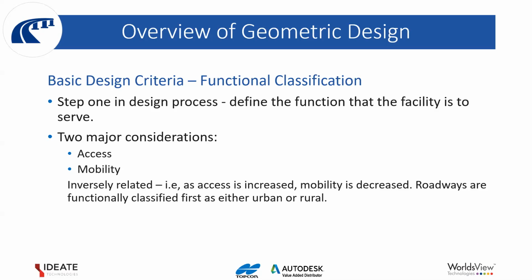In defining those parameters when designing a particular road corridor, access and mobility are inversely related, in that if you want to provide a highly accessible road, mobility will reduce. Very many access or intersection junctions getting into that particular road corridor lowers the ease with which people move from one point to another. And the same also, if you want to provide high mobility, the accesses must be limited.